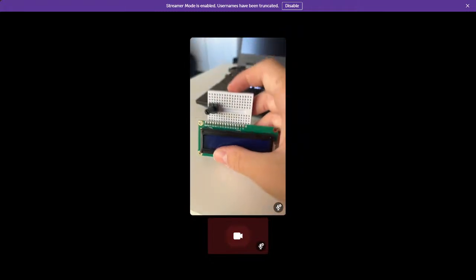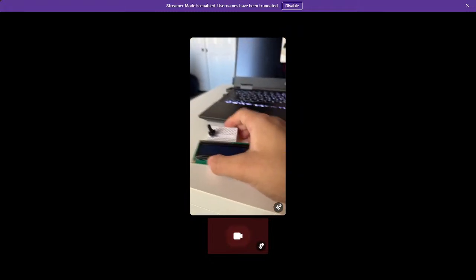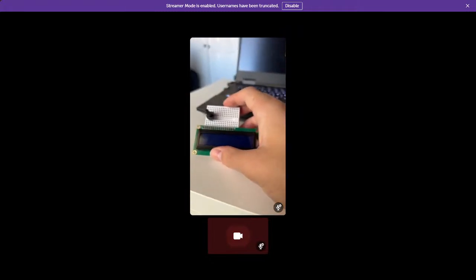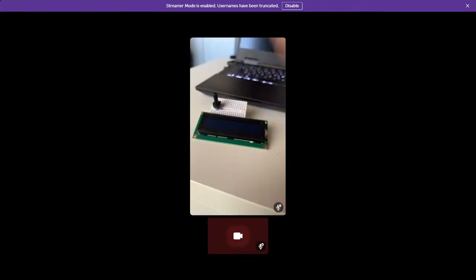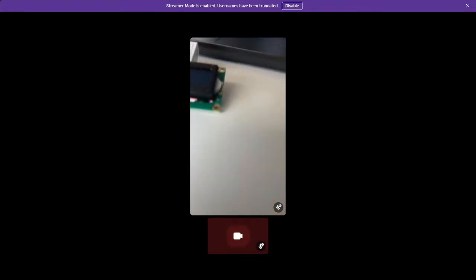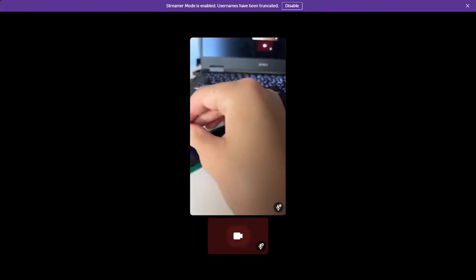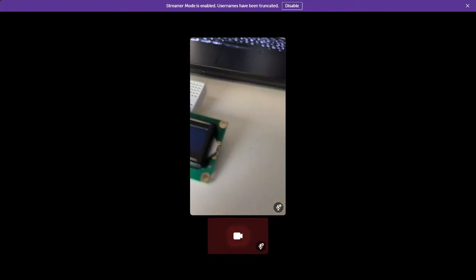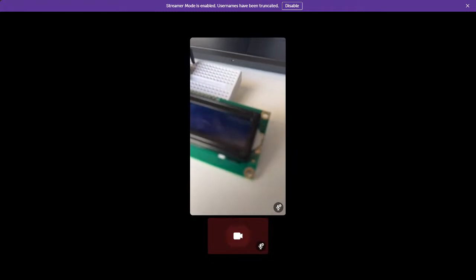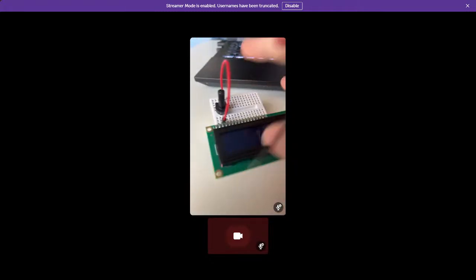Okay. So now that we've bridged it across the gap, we have this. So it's directly connected to the contrast pin, basically. So we're just going to grab our power real quick. And this goes to the VDD right here. We can just plug that in, connect it to here. With the ground, we're just going to connect that to the left pin.